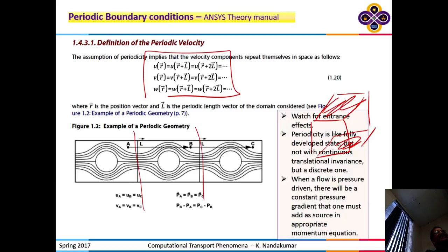That's a finer question. If the pressures are the same at these two points, what is driving the flow? Which force is driving the flow? It is the pressure gradient that must drive the flow, right? If I have a periodic array and it's a channel, I need to have a pump here to push the fluid through, right? And so that means I'm spending some energy overcoming friction at all these solid surfaces through viscous dissipation, right? In that sense, the pressure here cannot be the same as the pressure there, right? Because there is a pressure gradient.